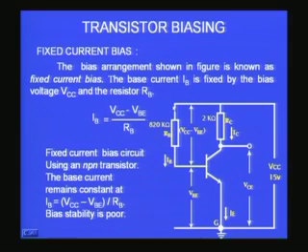So, now the same VCC is providing the IB as well as the IC that I require. So, this is a very simple scheme of biasing the base by providing a constant current for the base. For considering this type of biasing circuit, all the knowledge that you need is just simple Ohm's law and some basic circuit ideas like the KVL and the KCL.